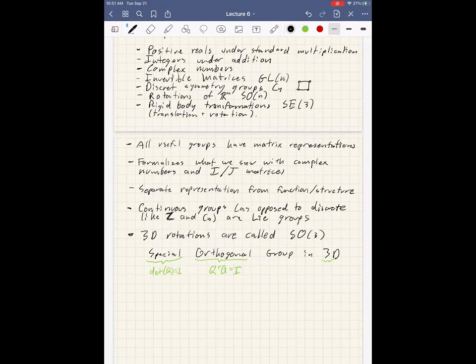Okay, yeah. When you say the matrix, can you not have a non-linear group? What do you mean by non-linear? An operation that's non-linear. In reality, all of this stuff is nonlinear. Rotation matrices don't commute, order matters, and they're not a vector space. I can do roll, pitch, and end up here, or pitch, roll, and end up in a totally different place. They're quite weird. They're not vectors, they don't add like vectors. Most of the things we know about them are not linear in a very deep sense that we're going to get into in a second.